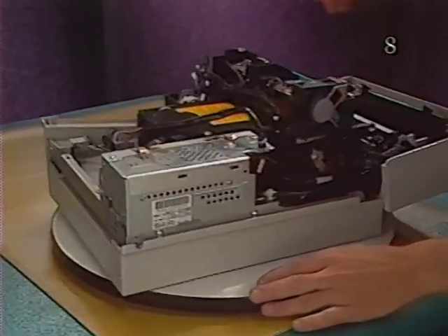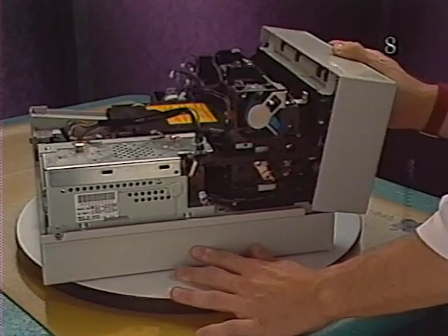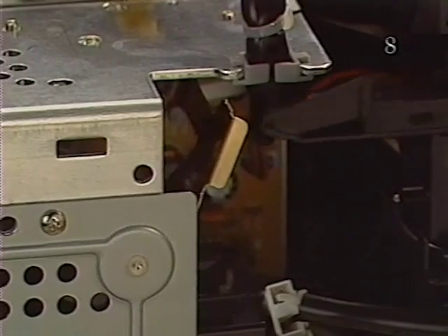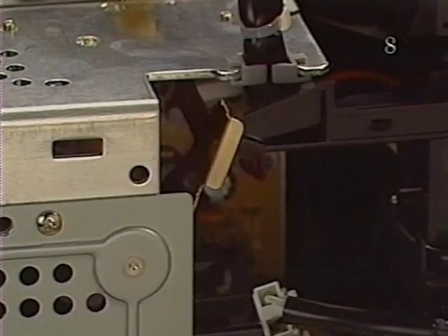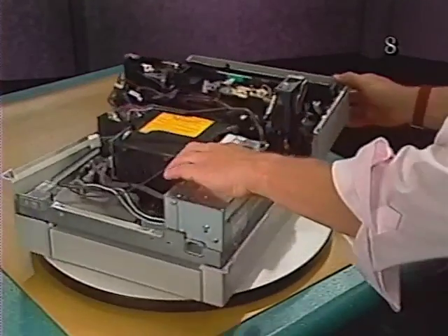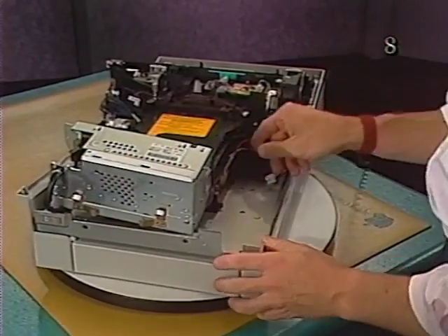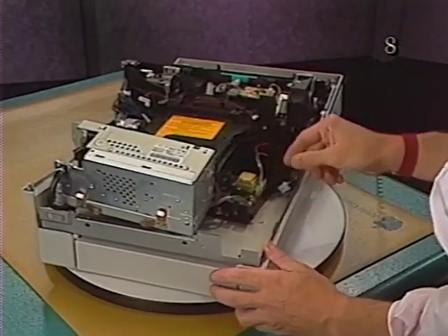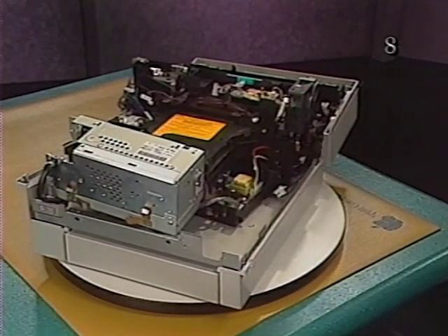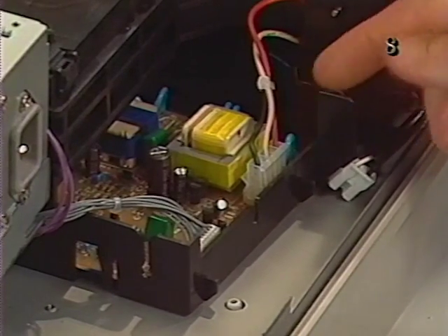Next is a fuser assembly power switch SW101. It cuts off power to the fuser assembly heater bulb when the front access door is opened. This is the high voltage power supply PCB. It provides high voltage to the primary and transfer rollers and the developing cylinder.